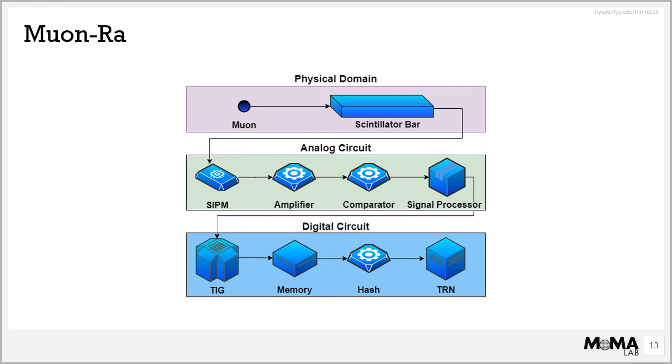Once enough entropy has been accumulated, the post-processing stage is initiated to eliminate bias. This, in other words, means that the gathered entropy has to go through a hash function. The output of the hash function is eventually stored in a final buffer, which contains all the true random numbers generated by our design.